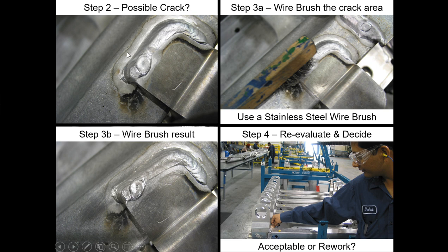So let's have a look at this scenario where something gets looked at, with an aluminum weld. This is an aluminum weld that was executed, and it makes it to you for step 2, which step 1 was putting the weld in. Step 2 is the examination of it. This weld started here and went around the corner in step 2 and did a termination maneuver that's very common in automotive, where we create a weld that's basically the start and the beginning are almost the same.